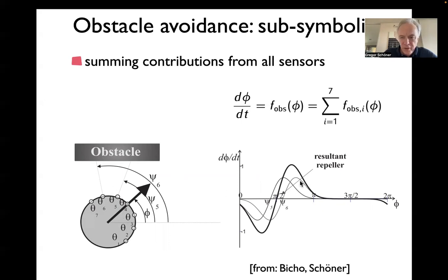And you see that their repulsive forcelets are superposed, so that the repeller is sort of in the middle between those 2. So you would be having here a repeller that goes about in this direction, and we tune these parameters so that what is being avoided is something that goes about plus minus 180 degrees from that direction. So you would be pretty much avoiding something almost, this would be like maybe the left and that would be the right, or actually the other way around, left and rightmost boundaries of the range of repulsion. If you look about here and about here.